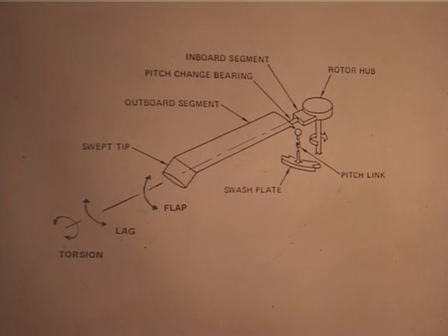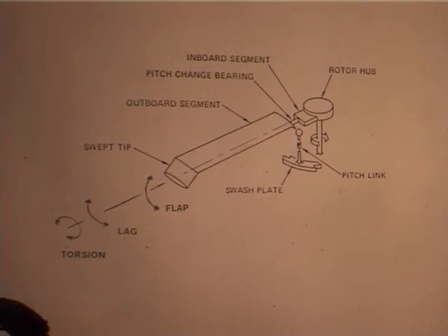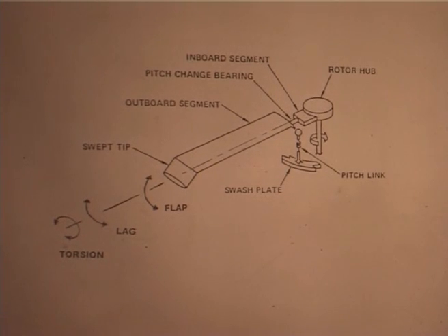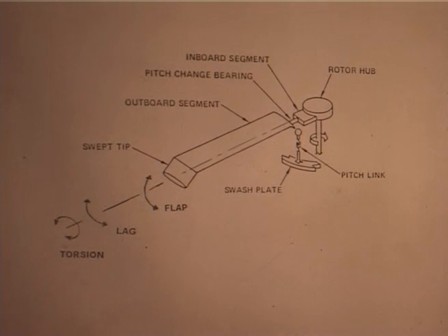Pitch angle you change at the root of the blade, but the blade also can twist elastically. Okay. That is equally important when you are analyzing the actual blade, because your angle of attack changes. Now, this is a large aspect ratio, in the sense usually it is about 20-25 feet.